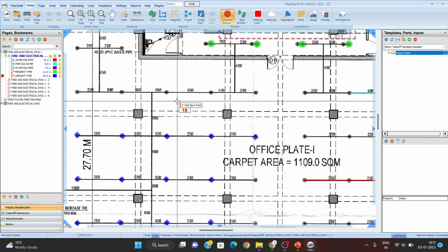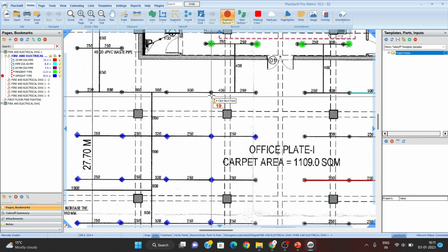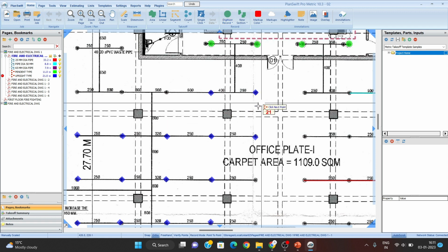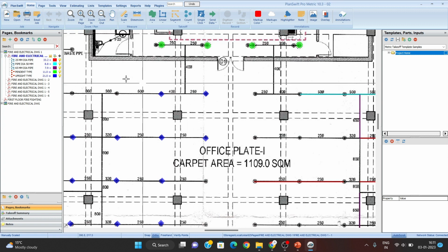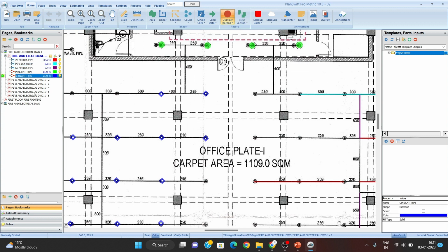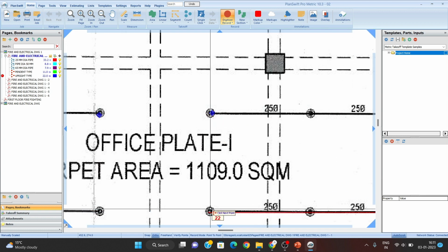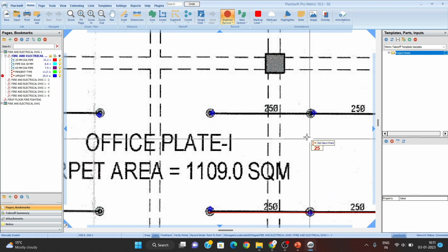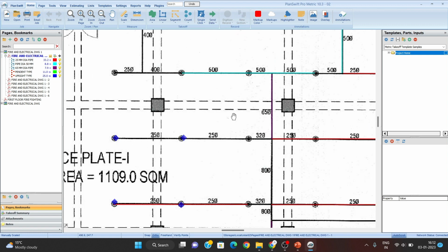See, it is counting, and it is showing 19 here, and here it is also shown 19. Whatever data you are taking is shown here. If we want to start counting again, go to the digitizer, select count, and then select, select, select. To exit, either press the mouse right button to stop or the escape button. Yes, you exited the program.